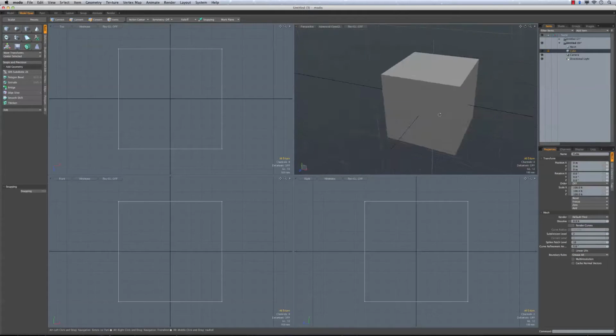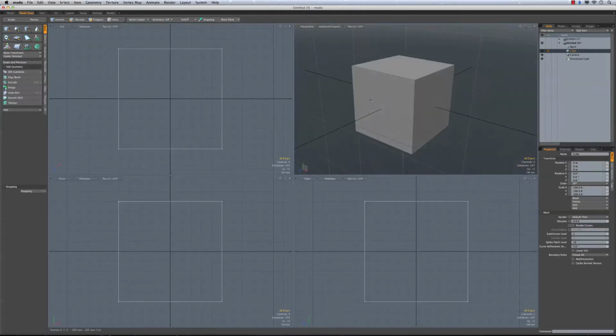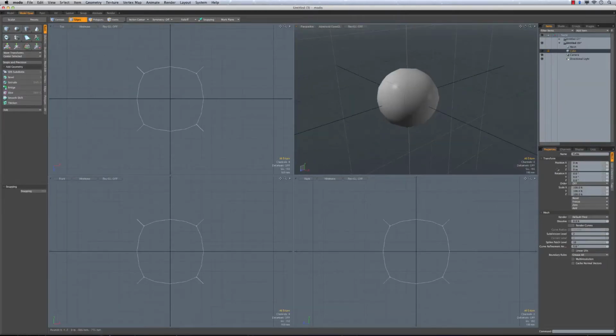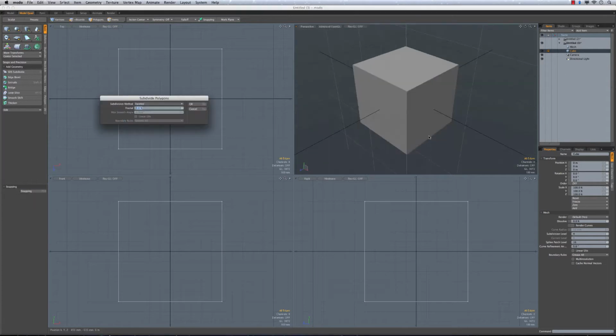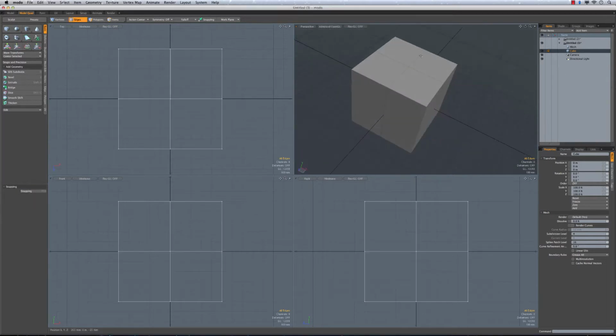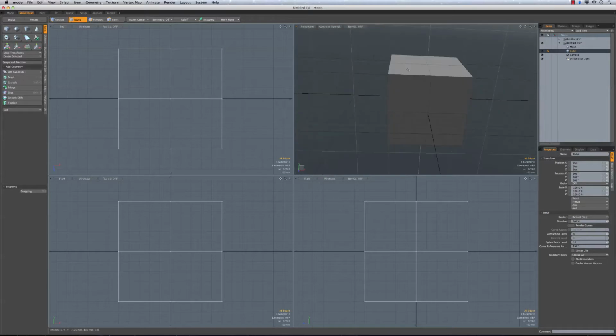All right, so let's actually just back up here, and I'll just create a new box, and we'll hide that sculpted one. And again, I'm just going to go ahead and get us back to where that first one was. So we'll subdivide, step up to level 4, Shift W, and turn ourselves up to a weight of 40. Then Shift D to facet that and add in an extra set of edges.